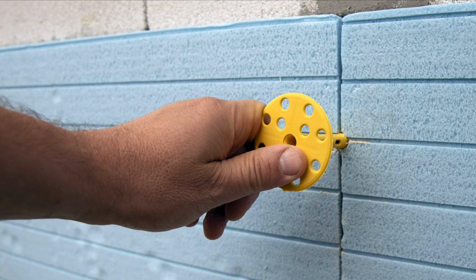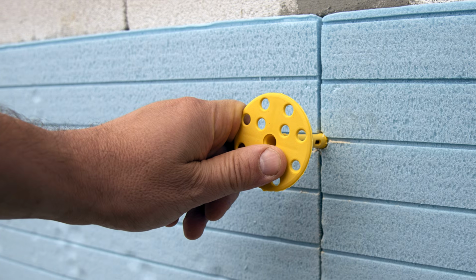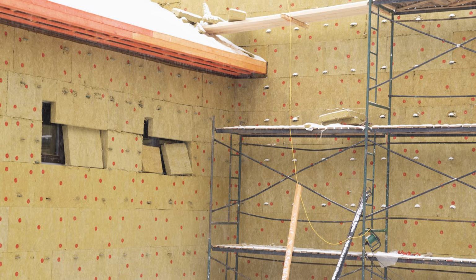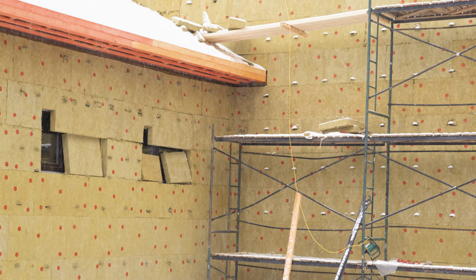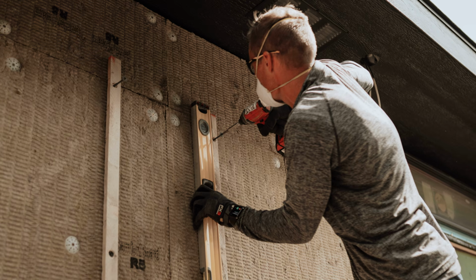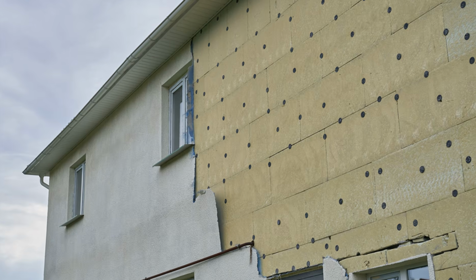So moving forward, we want to reference the condensation control ratios that the code is based on rather than the code minimums if we want to protect our buildings from moisture problems. Remember, the code is the worst possible building that you can construct by law, and if you want a durable and comfortable home that will last a long time, we need to know when to go above and beyond the code.